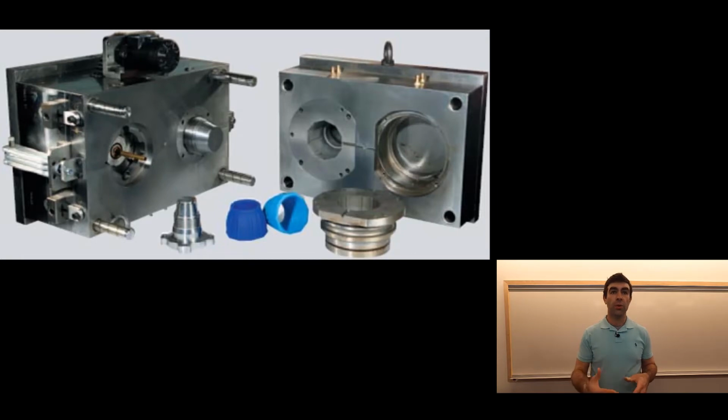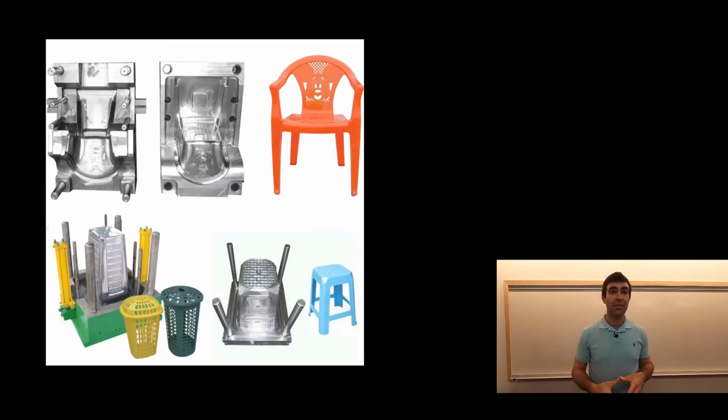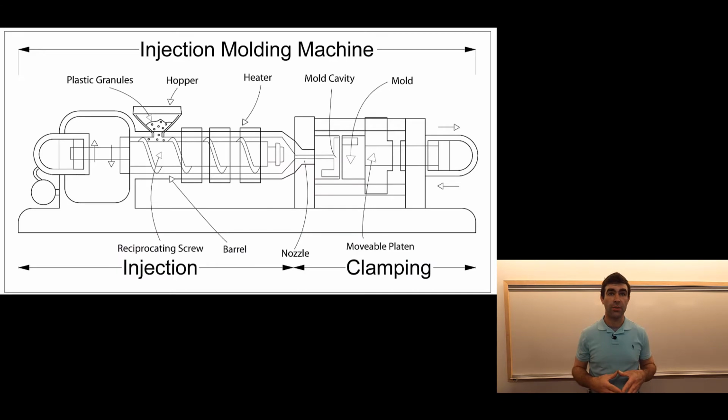The material will take the shape of the die cavity. It's going to cool down, usually with forced cooling in the die. So the die will have some kind of cooling system, usually just water running through it. When the part has cooled down enough to just keep its shape, right? It doesn't have to be fully hardened, but just enough so it doesn't deform.